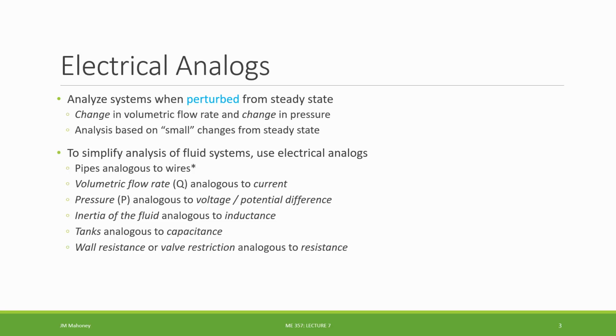Tanks are going to be analogous to our capacitance in that, again, the impedances are going to look similar. We have a 1 over S term with our capacitors in electrical systems, and we're going to have a 1 over S term in our tanks.